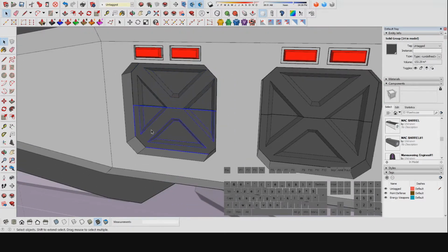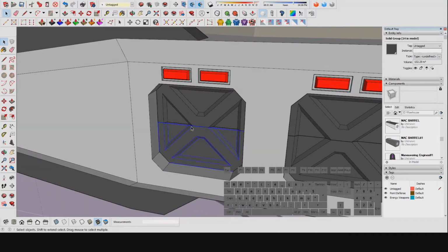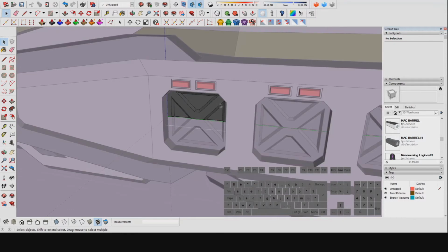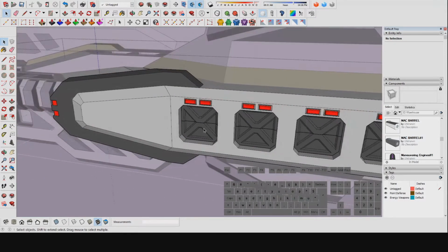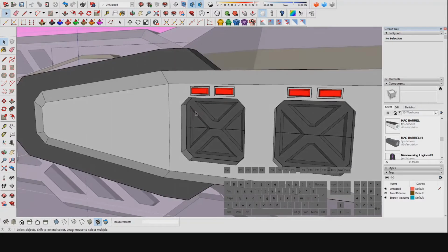The only difference is the added effect with components is they are edited across the whole model. So wherever that component is, if you edit one of these, for instance, if this was a component, then it would modify all of them. That's the only difference. I typically don't like using components, actually I don't have a really good reason. I think it's just out of habit, really.